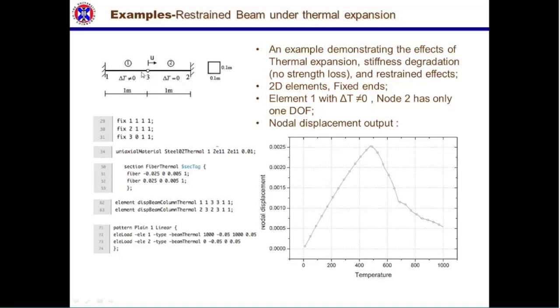It comes back. This is material degradation happening, the stiffness loss at high temperatures in the heated member, and the elastic member on the other side then pushes the member back, pushes the node back. So this is an interesting benchmark test. At the moment, we only have this as stiffness degradation, not the yield strength, which is not bringing plasticity in, but we can do that as well, and that can also have an analytical solution, and it also allows us to check the nonlinear material behavior, including, say, nonlinear geometric behavior here.